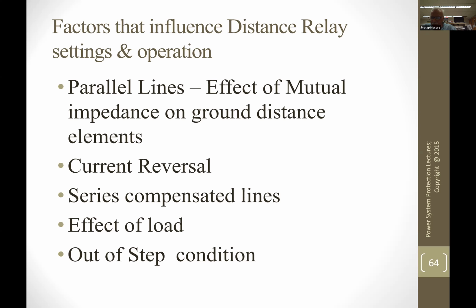So yesterday, somebody asked what happens if there is load. Load is taken as a positive sequence current, so you have to add that, and then it gets subtracted from the negative sequence for a phase-to-phase fault. Then you have to look at how that affects it.